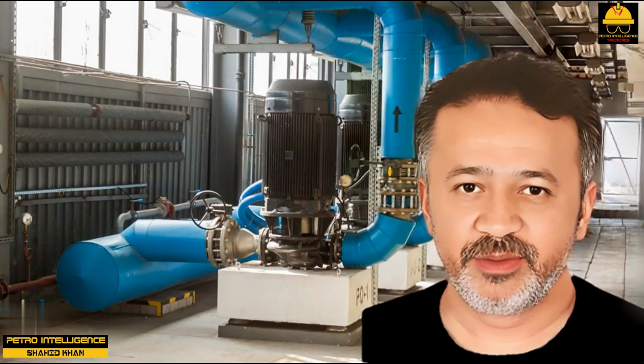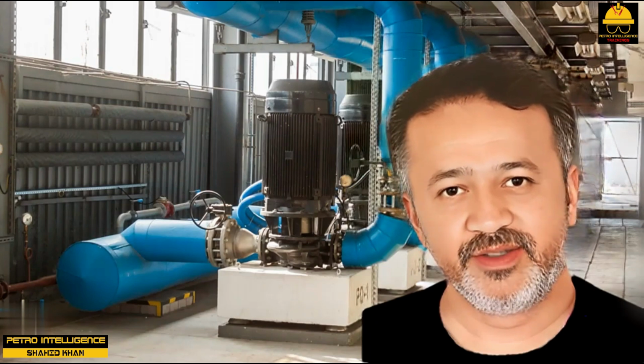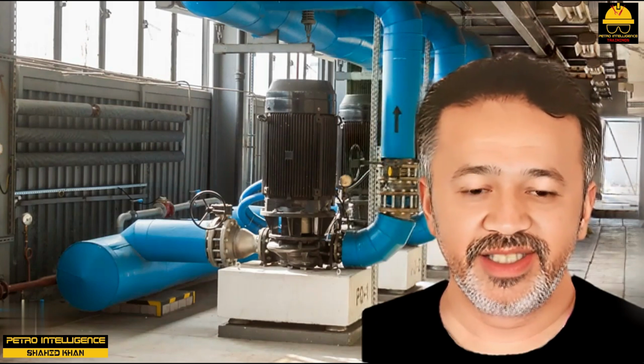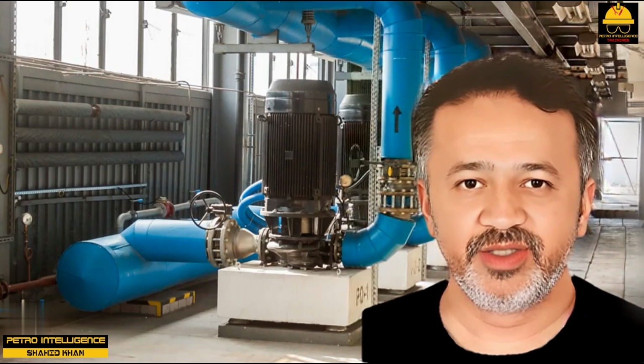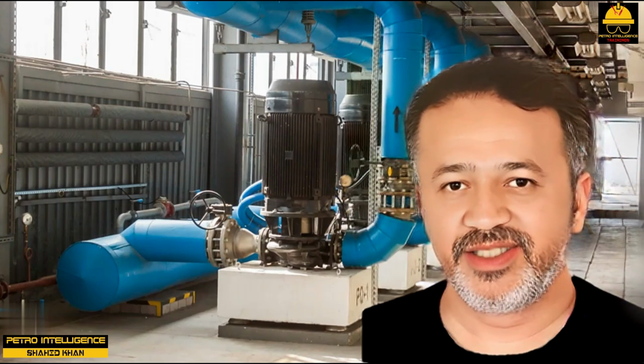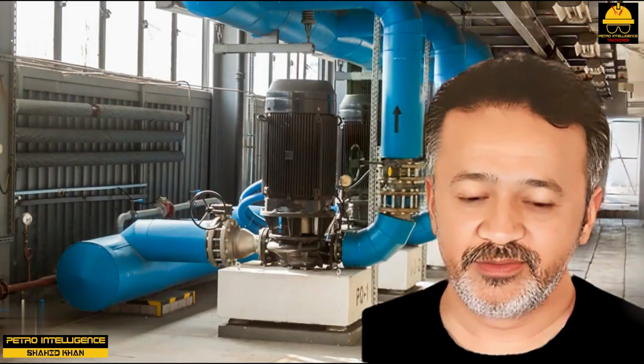We have usually kept impeller sizes in our revamped designs 0.25 to 0.5 inches below maximum. I don't recall anyone complaining that such pumps vibrated as a result of the enlarged impeller. On the other hand, for a new installation, now that we have learned of the Exxon standard, we plan to follow it in our process design work.